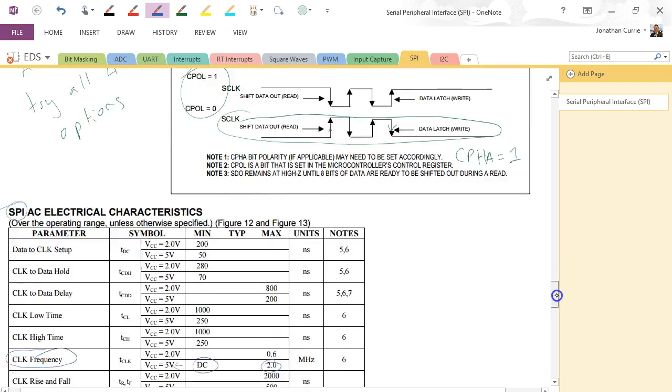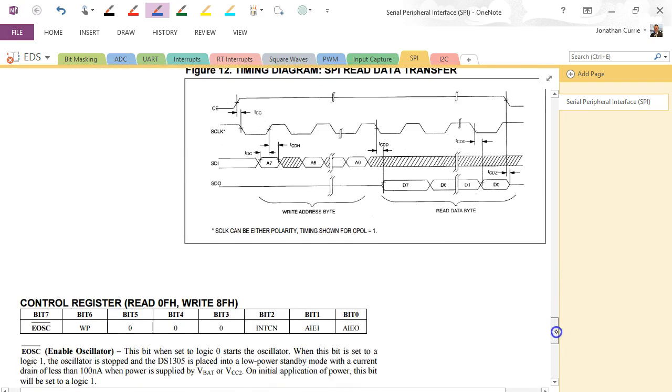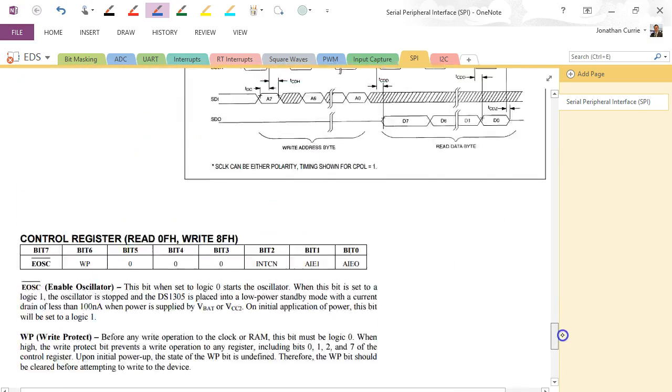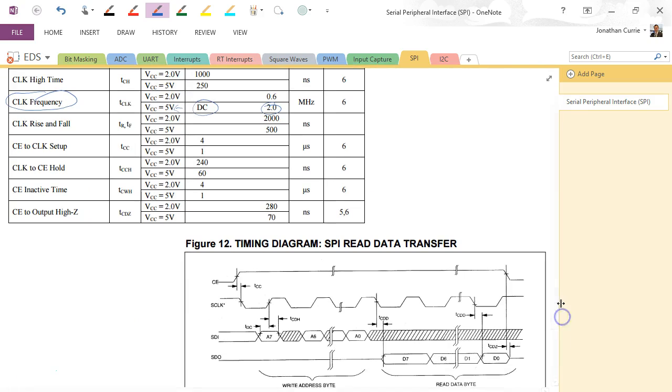The only thing we also need to now consider is the actual device itself and how we read and talk to that. One of the most critical things is this delay here. You can't just go, for example, CE equals 1, SPDR equals data. Not going to work.